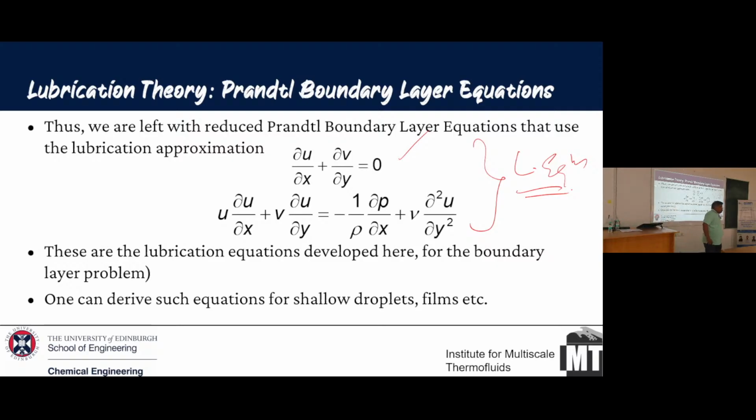Yeah. So that's a good question. When we consider evaporating systems, or a base state which is not constant, there are two methods we use. One uses severe assumptions. The first assumption we make is called a quasi-steady state stability analysis. We freeze the system in time. So we do the simulation, we freeze it each time. That assumes that the rate of evaporation is so slow that it is slower than the time scale of the instability. So at each frozen state, we'll do a stability analysis.